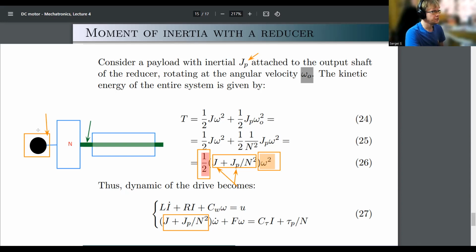Okay, so the reduction of this coefficient, the rate of change would also be 1/n, right? So of course it shouldn't be like the same torque should have more potency. As we said, torque acting on the output shaft is n times higher. So in terms of output shaft, we expect its inertia to be less important. We could rewrite all this equation in terms of omega sub O, and then n squared would appear in front of this guy.